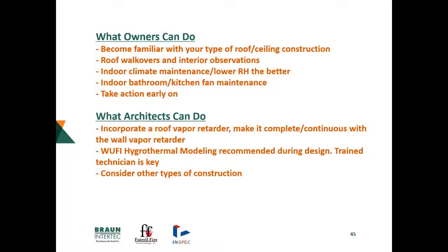Maybe pay a little more attention to the roofs by walkovers, interior observations for mold, helping with that indoor climate maintenance, making sure you're operationally good with your HVAC packs, bathroom and kitchen fans are working, filters are clean, all trying to keep that RH down to avoid moisture going up into that area of concealed space. If you see something, take early action, to try to avoid what could be, in a couple of our investigations, an actual roof structural failure.